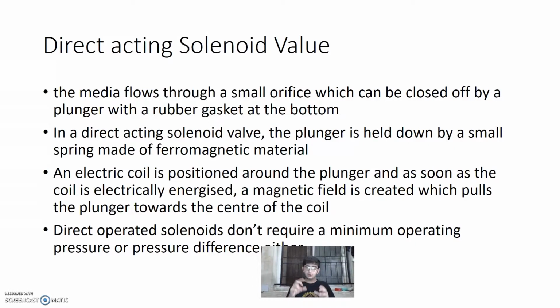Now to make a normally closed solenoid valve, you require a spring attached to the plunger, which always pushes the plunger downward, right? So we require some amount of force to open that valve, which will be provided further by a magnetic field. So a spring is attached to the plunger to make sure that our orifice area is always closed to prevent any leakage and to have a smooth mechanism, right?